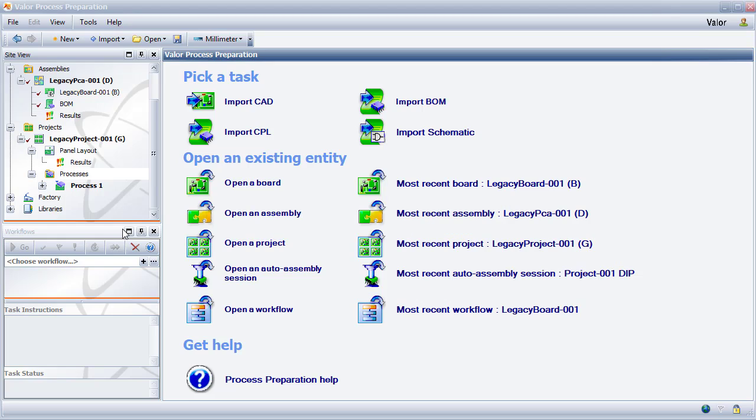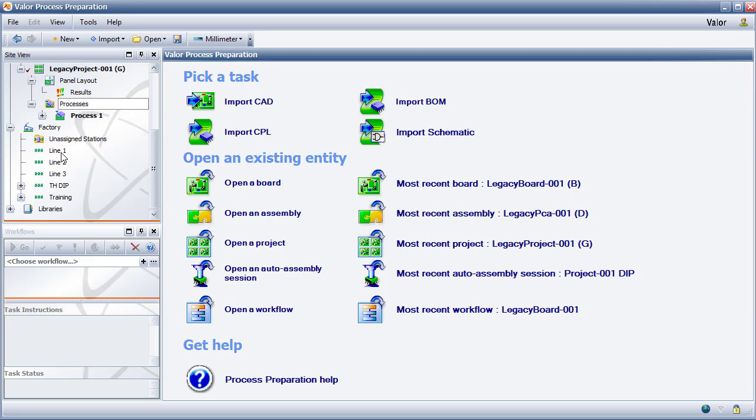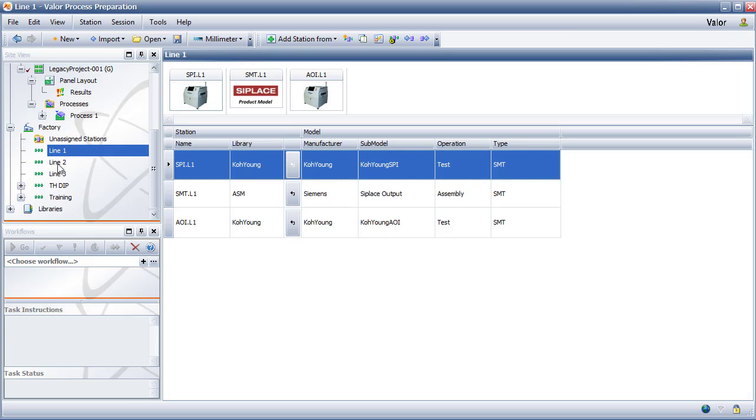Management of position and rotation issues on placement and inspection machines is traditionally a cause of problems during first article runs, that can be addressed with the overall placement and part library management capabilities of Valor Process Prep that we will see now. With the recent trend in single vendor SMT lines, optimization and balancing have become more the focus of the vendor software. However, this has also given way to mixed vendor factories that raises the challenges of part data management.